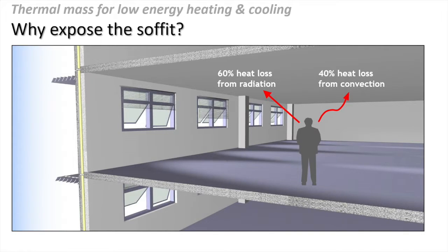And what that means is we can continue radiating heat to the soffit throughout the day, and it will hold on to that heat. And importantly, the soffit temperature will not increase by more than a couple of degrees, maybe 3 degrees. So even later in the day, when it's absorbed a lot of heat, it's still cooler than we are, and we can still radiate heat to it, so it's still providing that beneficial radiant cooling effect. So that's why we use concrete soffits. If it's a lightweight floor, it's going to warm up really quickly, and the effect doesn't last very long.